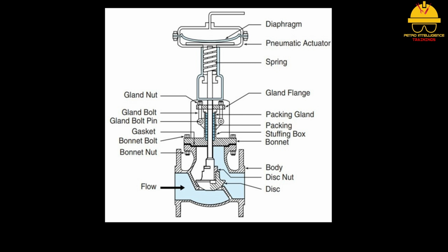on the design. The piston actuator uses an airtight cylinder and piston to move or position the stem. It is commonly used with automated gate valves or slide valves. It is used where a lot of stem travel is needed. Vane actuators direct air against paddles or vanes and are frequently used on quarter-turn valves.